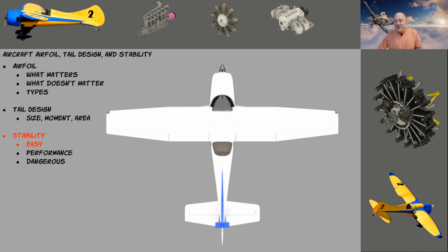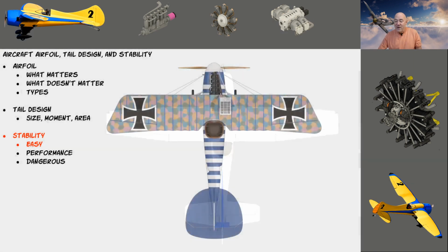I'm not going to judge you. That's just not the way I do it. I've seen these airplanes fly like complete garbage. And I don't want to sound egotistical, but you give me an hour with it and I get the center of gravity right and the throws right, these things fly like Cubs.